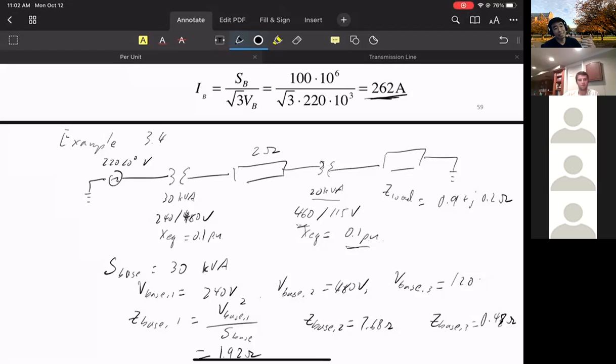Then if you look at the ECE building, that's 480, right? So it goes in multiples. That's why we pick nominal base voltage this way. But this is the convention. Yes, go ahead. Hi, Professor. I think the reason we choose the 120 volt for the base is because 480 over 120 is the same turn ratio as the T2.